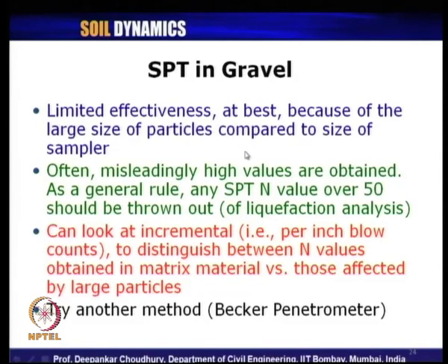So, what is mentioned mostly for gravels is that we should try another method, which is called the Becker penetrometer test or BPT. Standard penetration test is good for sandy type of soil, whereas BPT is good for gravelly type of soil.